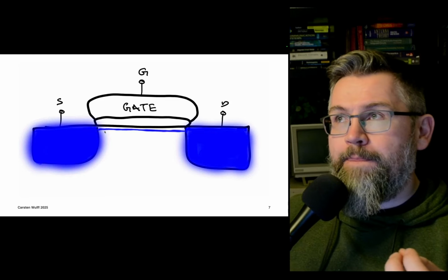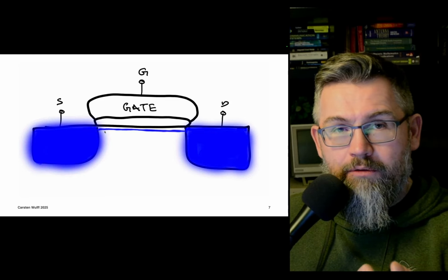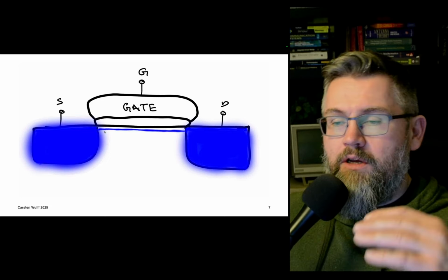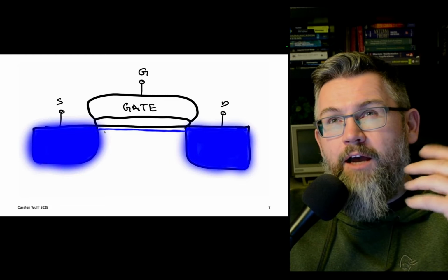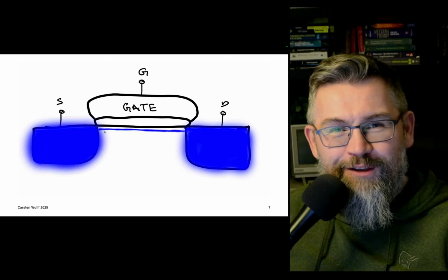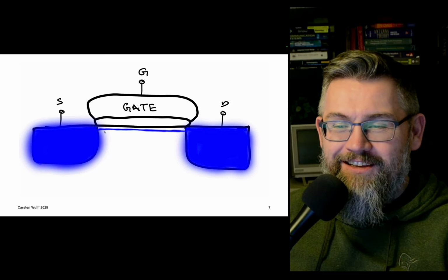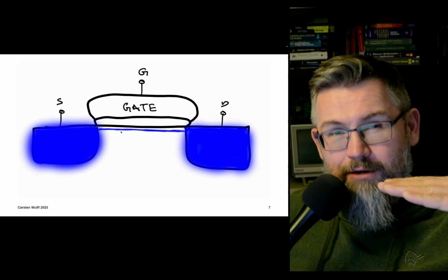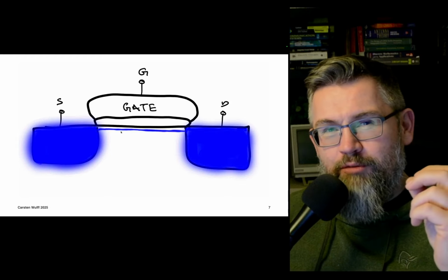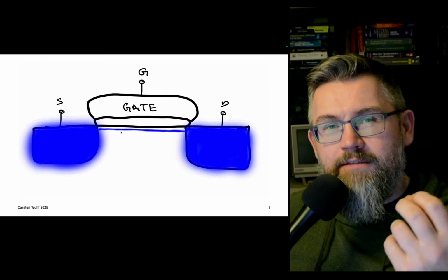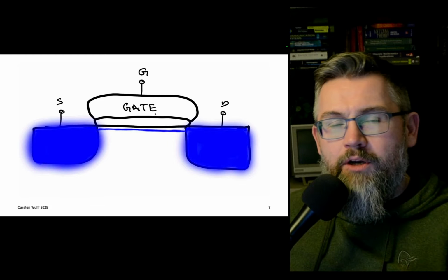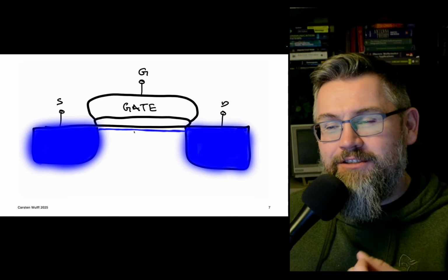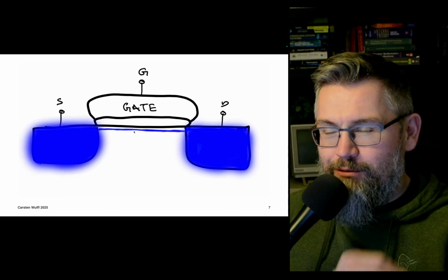there is a thin, like a few nanometer thin, sheet of free electrons that gets, I think the right word would be made, underneath the oxide in the silicon. It's not exactly at the surface, it's slightly below the surface. And that's actually determined by quantum mechanics, where the actual density of electrons are. Now, if you want to look at why there is this thin sheet of electrons, we have to go to quantum mechanics, and we're not going to go all the way today.